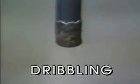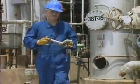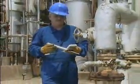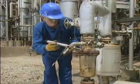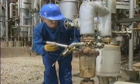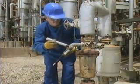And although an inverted bucket trap usually discharges condensate intermittently, it may have a constant small discharge if it's operating at a very low percentage of its rated capacity. This condition is sometimes called dribbling. By combining the information you get from performing temperature, sound, and visual inspections that you make during a trap survey, you can get a good idea of how well a specific trap is working.